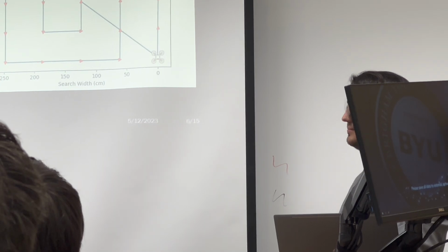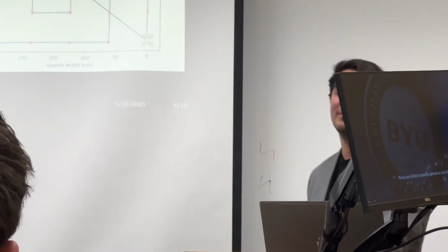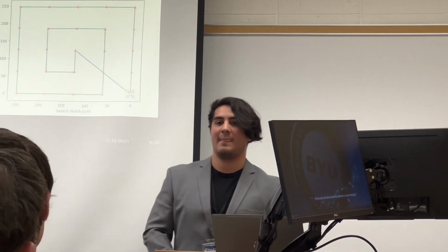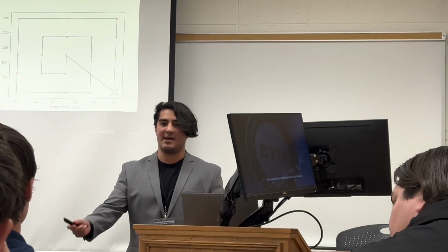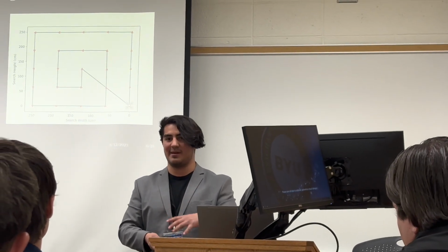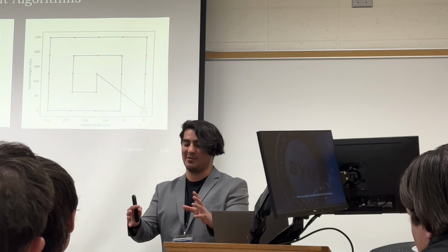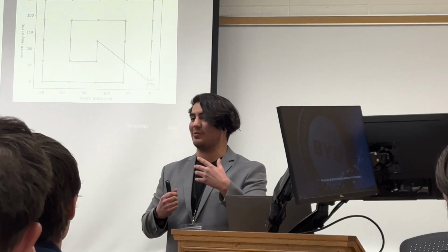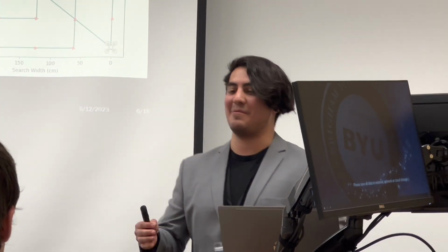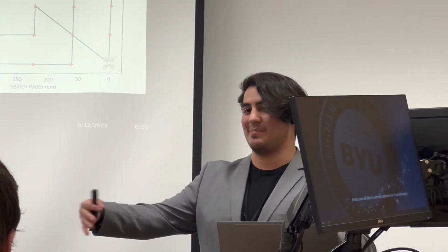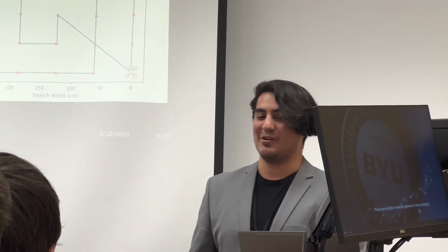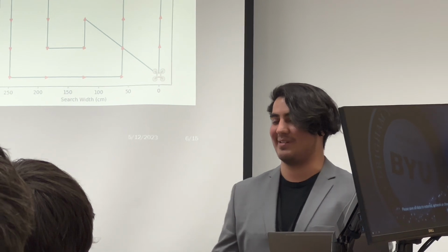I believe there were 2 more questions here. So the drone you're using only has a forward-facing camera and maybe a downward-facing one? Yeah. The downward-facing one is what we use to land on the helipad, so it's able to finish where it starts. If we use the white drones, which don't have the bottom camera, and we tell it to land on the helipad where it starts, it'll be a few feet off because, even though the drone's keeping track of its course, it's not super accurate.